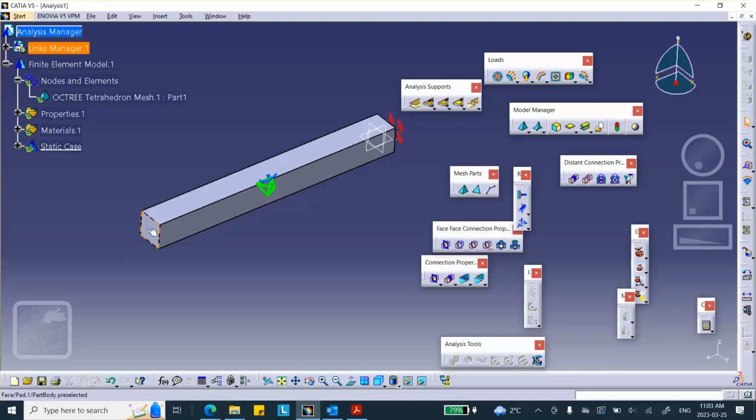And what I'm going to do is apply a load of 1 pound here. This is a dummy load of 1 pound. And once I do the buckling analysis, that buckling factor, whatever it comes out to be, you have to multiply 1 pound by it to get the buckling load. If I had put, for example, 100 pounds here, no problem. It's just that the buckling factor that you're going to see in the tree later in the selection tab is going to be 100 times smaller than if you had put a 1 pound there.